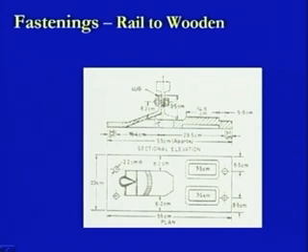Now, when this rail section moves, depending on whether another gauge face of a rail section is provided on this side, it will get connected to the other rail section. As soon as it gets connected, it allows the change of direction of a train. So, this is used at those locations where the change in direction of a train is to be provided.